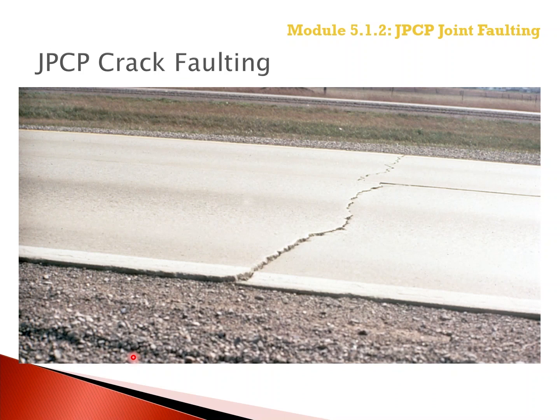Faulting can occur along mid-slab fatigue cracks, as shown in this photo, but only faulting along the transverse joints is predicted by the Pavement ME design software. A point to remember: faulting has a significant impact on the measured IRI values. The Pavement ME design software, however, only uses the faulting predicted along the transverse joint to estimate the IRI along the project.